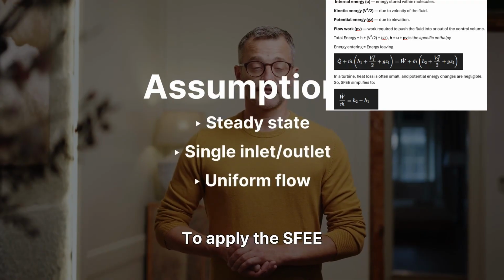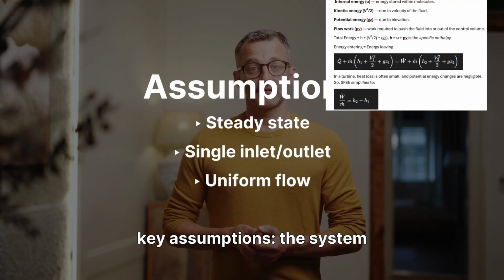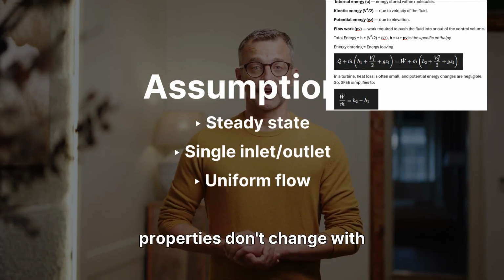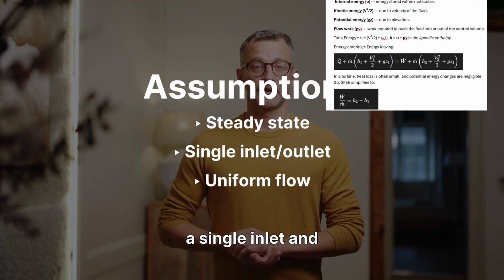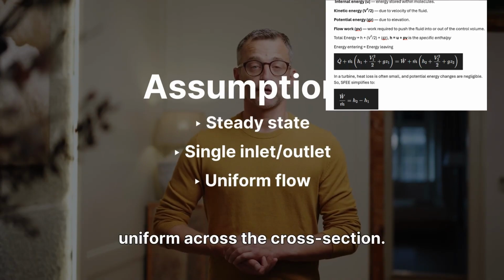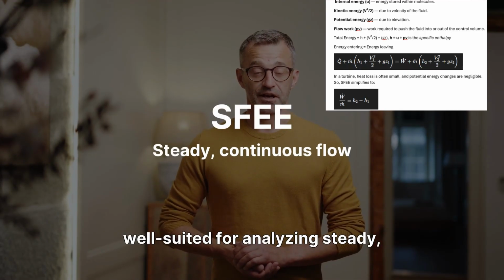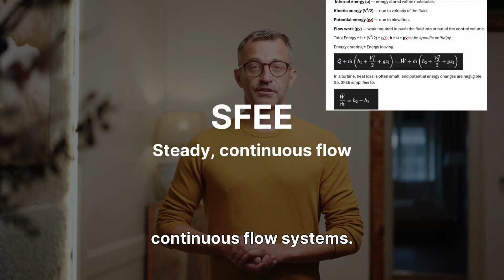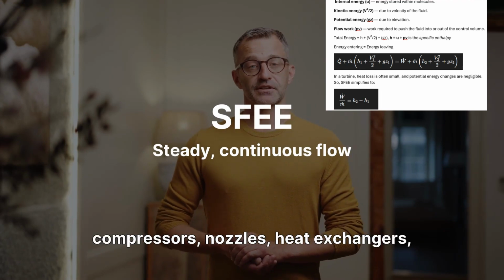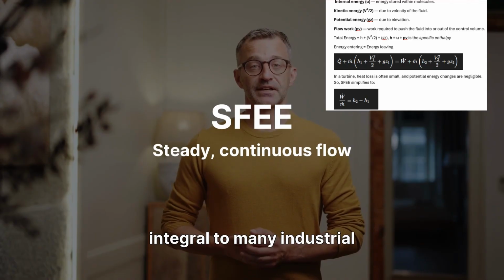To apply the SFE correctly and accurately, it's crucial to remember several key assumptions. The system must be operating in a steady state, meaning properties don't change with time. There should be a single inlet and outlet, and the flow at both the inlet and outlet should be uniform across the cross-section. The SFE is particularly well suited for analyzing steady, continuous flow systems. These include common engineering devices such as turbines, compressors, nozzles, heat exchangers, and pumps, which are integral to many industrial processes.